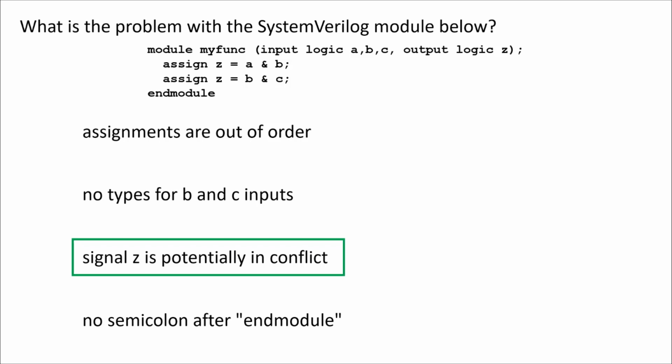VHDL actually has 9 values. It was 9? Okay. Looking at this Wikipedia article, I've used this later. So in VHDL, I've used dash, which is don't care. U is undefined, and then of course there's still a Z and an X and a 0 and a 1. I also have W, L, and H for weak drive as unknown, logic 0, logic 1.